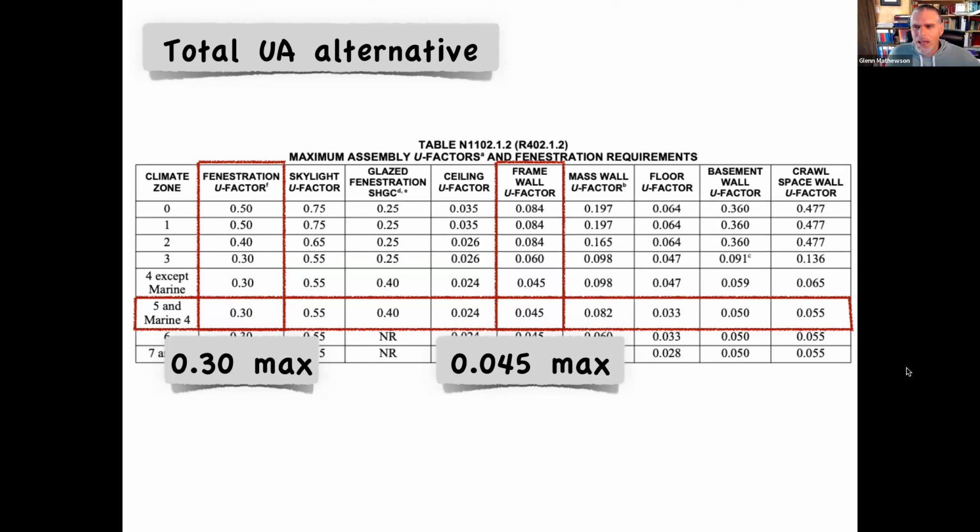But let's say you've got a different plan. Let's say you're designing a house with a little reading nook on the second floor. I've seen this. A friend of mine's got one of these in his house. It's a tiny, small reading nook up there, but it's already kind of a small space, and you're really trying to maximize the square footage of that space. So maybe you want to build a smaller wall assembly in that area so that you can get more square footage and less thickness of wall. That'll be less insulation in that wall.